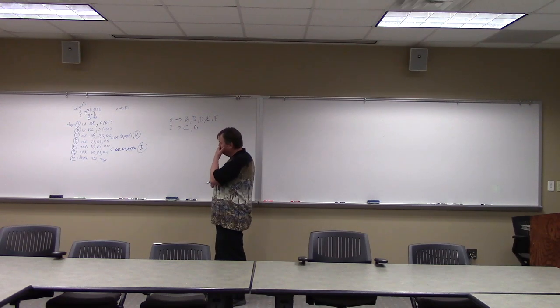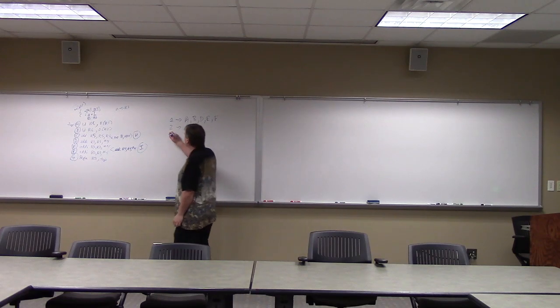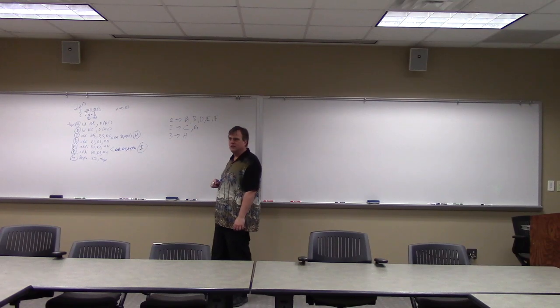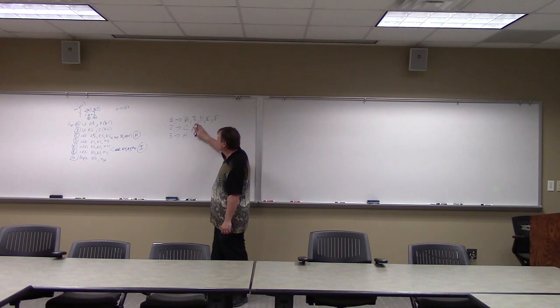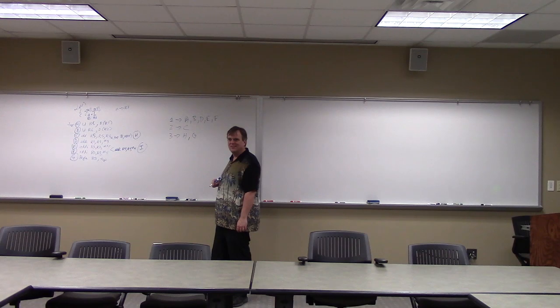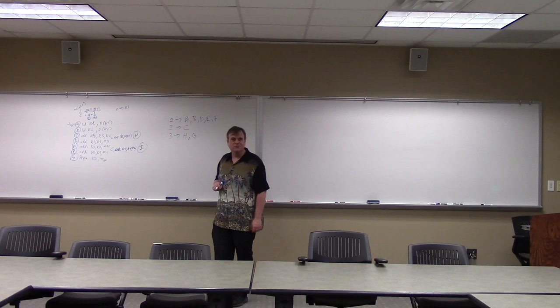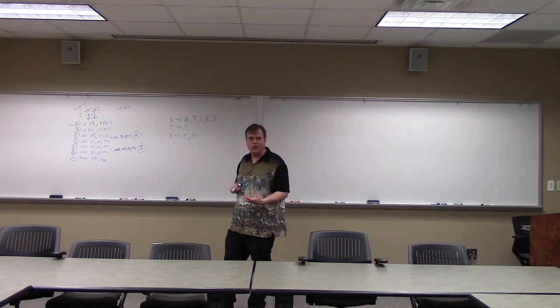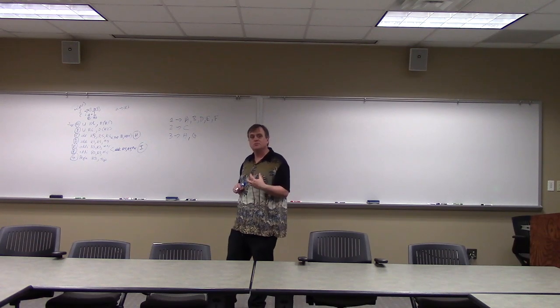That needs whenever C is done, R5 loaded. Does this change anything by putting H there? We haven't done anything to R5, but we have the branch, I guess. Why did I do what I just did? It's got to be in the loop still. It's a control hazard. So besides your data dependencies, don't forget the control hazard. I didn't tell you you have a branch delay slot, which would let you carry it after whatever. I just have to specify it's in the loop.